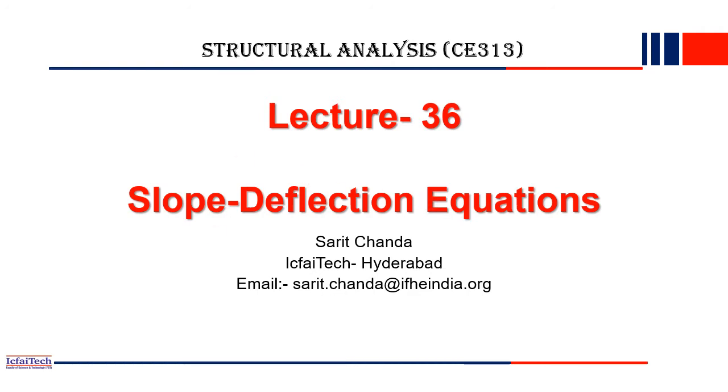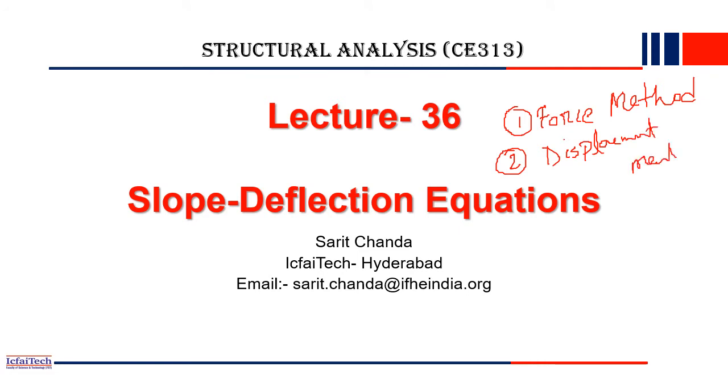So let's begin our derivation part first. So before starting derivation, let's understand few basic things about analyzing of indeterminate structures. So there are broadly two methods of solving the indeterminate structure. One is force method, and next is displacement method. So all the methods can be classified into these two large categories. So one is force method and next one is displacement based method.